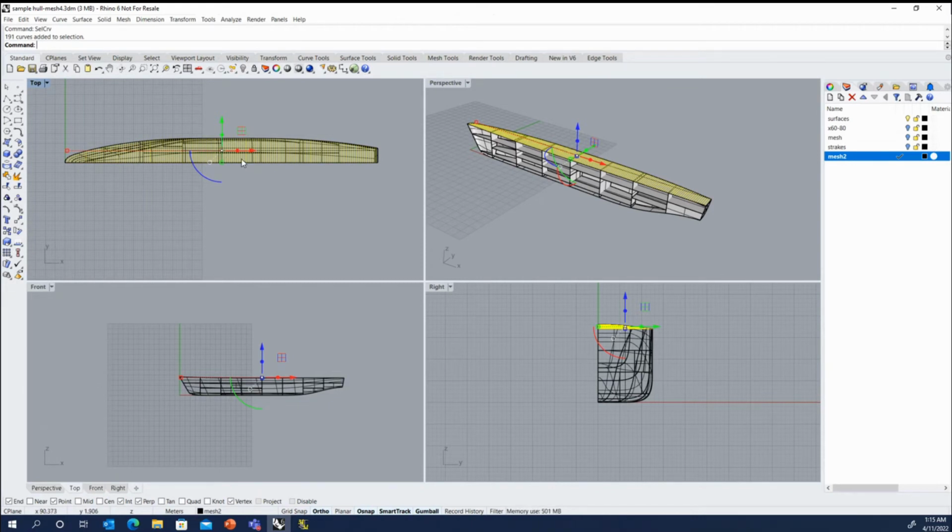If you don't give it a range, then it will create the curves to infinity in both directions. Because I could have given it a seed point at midships and a direction and a spacing, and it still would have done the entire length of the vessel, because it's using that base point as the location for one of the curves, but it's not the starting point of the curve. It's just the location of a curve. If you specify a range, then you give it the starting point and the ending point for where it's going to make those cuts. So you could use the contour command still for having that control if you wanted to vary the spacing transversely, but you'd have to execute it multiple times. And that's why, if you had an irregular spacing, sometimes using those physical cutting planes can be useful. So that's another alternative there.